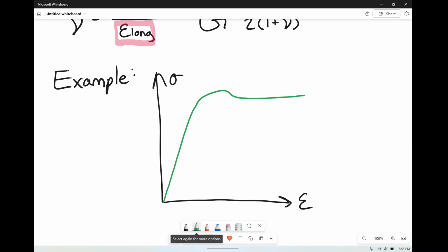Actually, quite frequently. If you realistically do a test on, say, something like steel, it's going to be a straight line for sure, but that little peaky area over here is sometimes not very well defined. So you just kind of stay out of that range. Sometimes it goes up and it dips down, sometimes it doesn't, sometimes it just kind of goes off at an angle. All materials are different because that's just the behavior of materials.